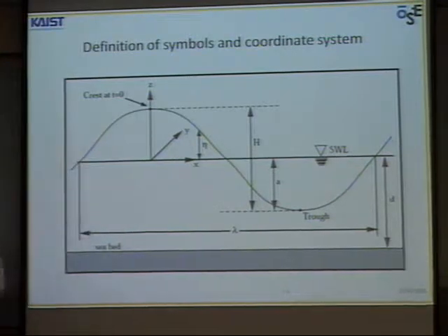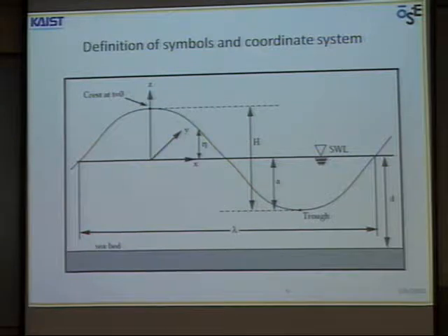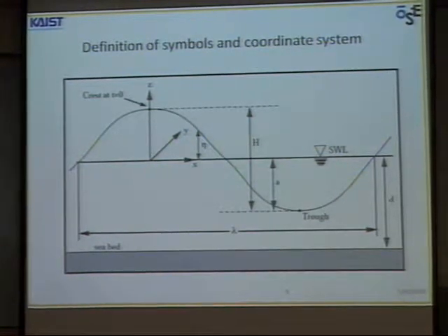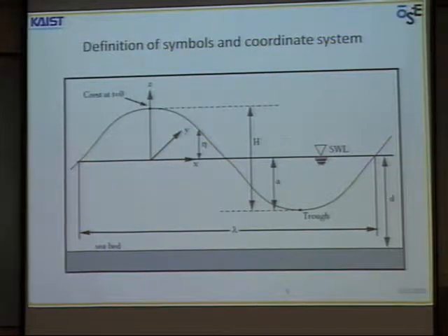So it's like this, and there are a few assumptions we make before we can proceed: homogeneous, irrotational, incompressible, inviscid. And since we are talking about wind waves, which are small scale, the Coriolis force, which is due to the Earth's rotation, we can ignore it. Otherwise, we're going to have a totally different governing equation.